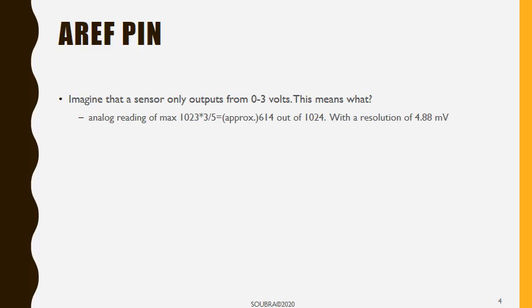All right. Anytime I ask you as an engineer, am I able to do something? You always answer yes, because we're always able to provide some kind of solution. Not the best one, but some kind of solution. This is your job. So yeah, we can improve the resolution, and this is where the AREF pin becomes handy.